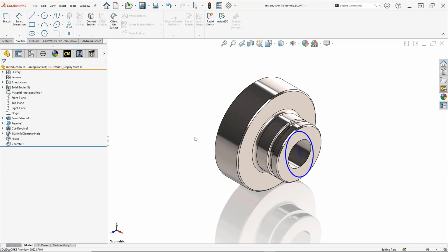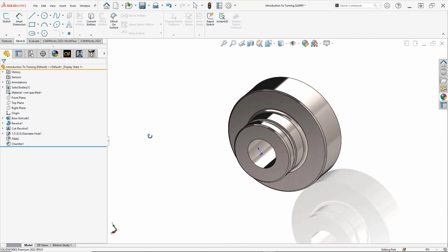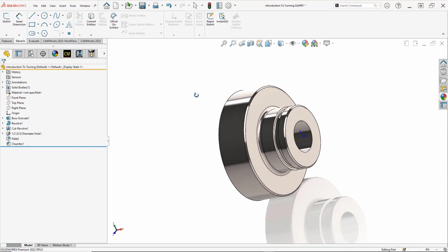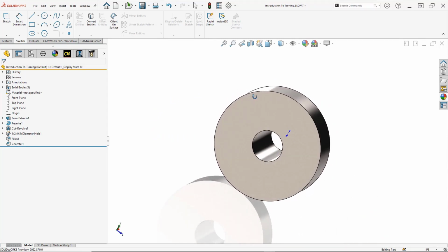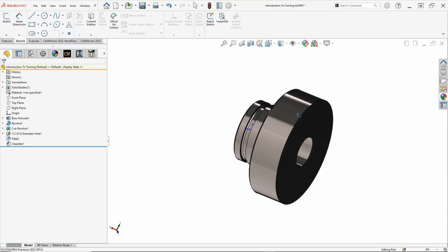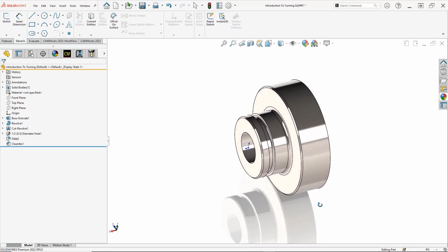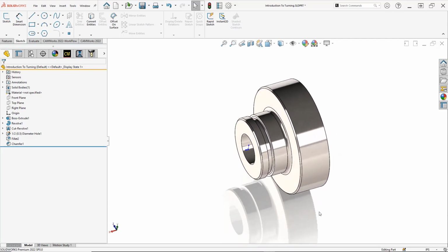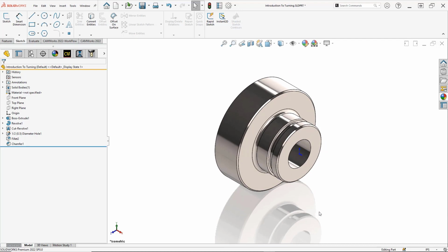When looking at this part in an isometric view, the SOLIDWORKS origin is established from the right face and center of the part. One thing to keep in mind is that if the part is created or imported in an odd fashion, and let's be honest here because it's happened to everybody, SOLIDWORKS CAM and CAMWorks don't care, because we will be establishing our own coordinate system, which properly orientates how the part sits within your machining center.